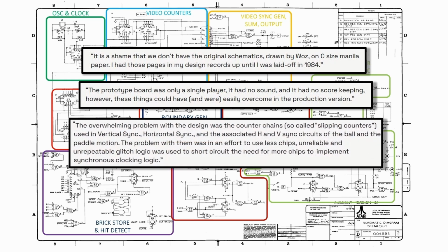Another thing Gary mentioned was issues with the video counters and sync circuitry. Now, I don't know what it was, but it could have been something like a self-referencing gate where you use that same short pulse to drive something else, like a reset or a load circuit. And that would completely depend on that particular chip's input characteristics, so it would be very unreliable.